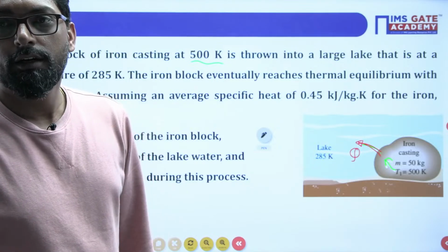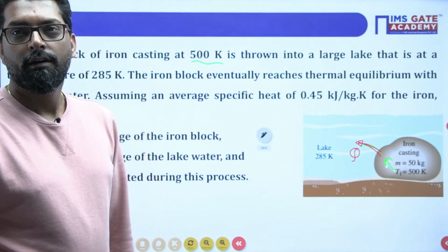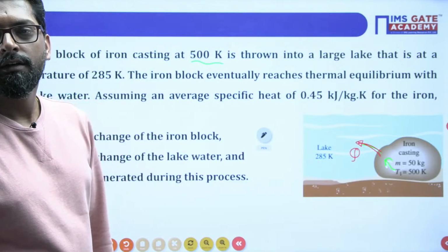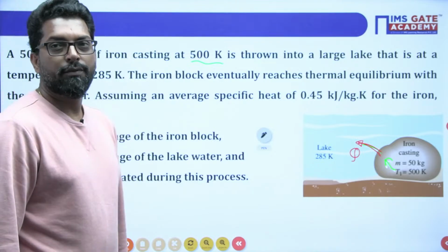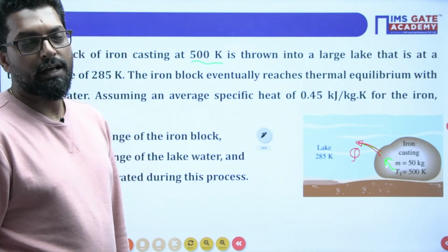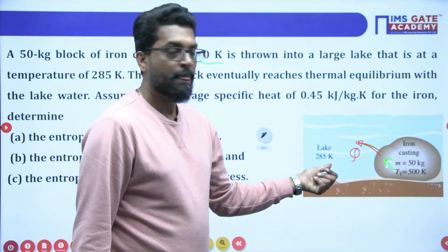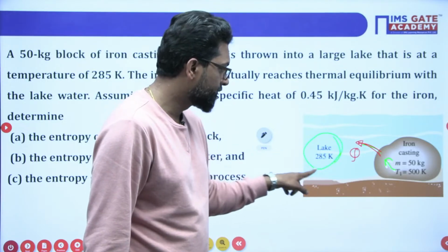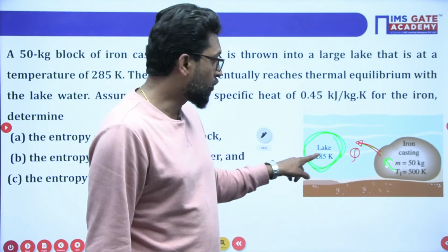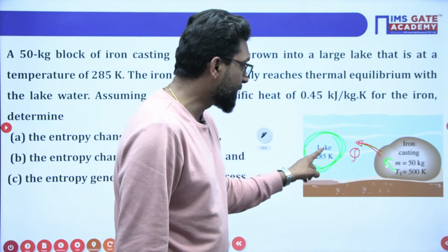What are you asking? The temperature of the control volume increases? No, the temperature will not increase. See, this heat will transfer through a large lake. Since it is a large lake, its temperature doesn't change. But the heat will be accepted by the lake.